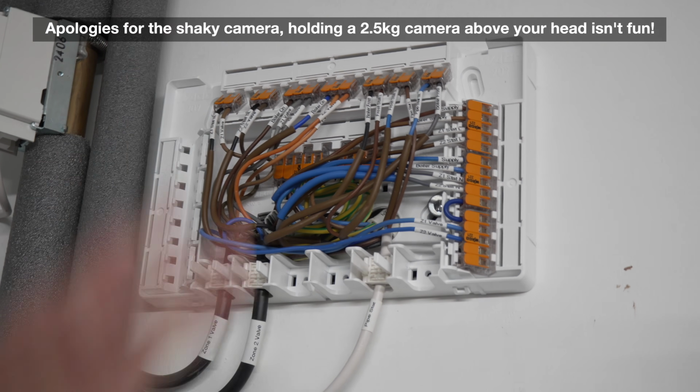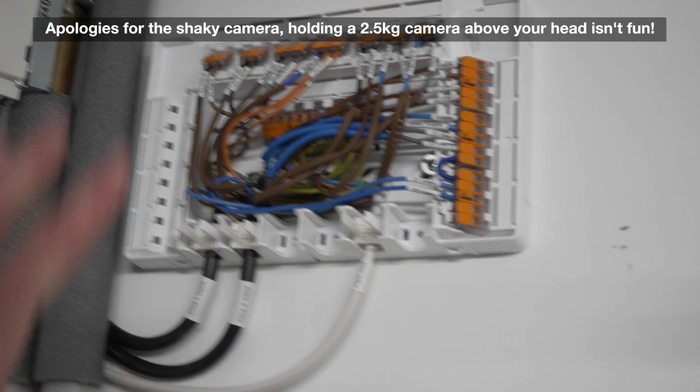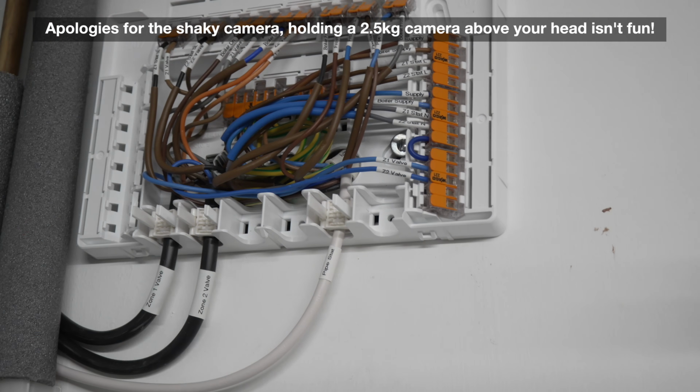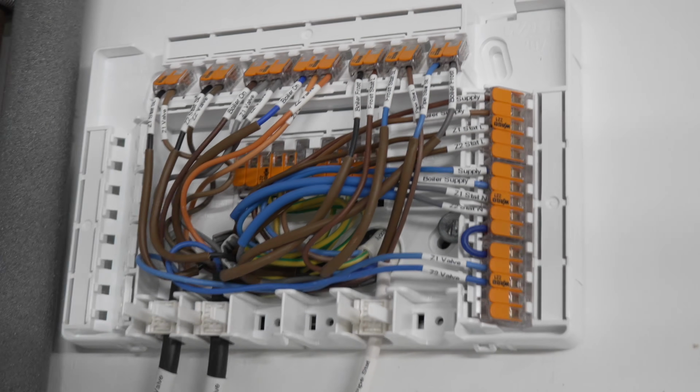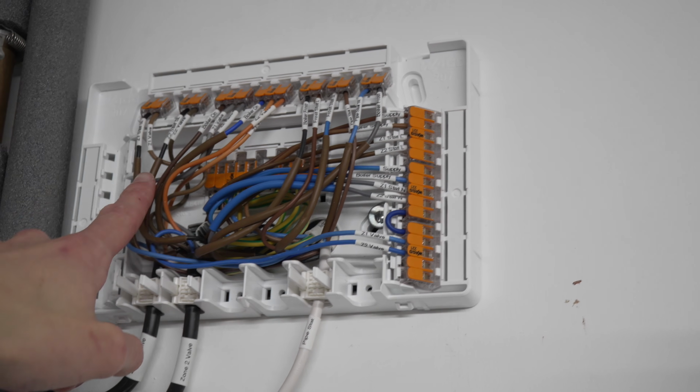Now of course, needless to say, once again, make sure everything is fully, safely isolated, you've tested it, you've checked it's all dead before you start touching any of this. But here we can see the inside of the wiring centre and an absolute ton of wires. Now, your wiring centre will not be as neatly laid out as this or as labelled as this.